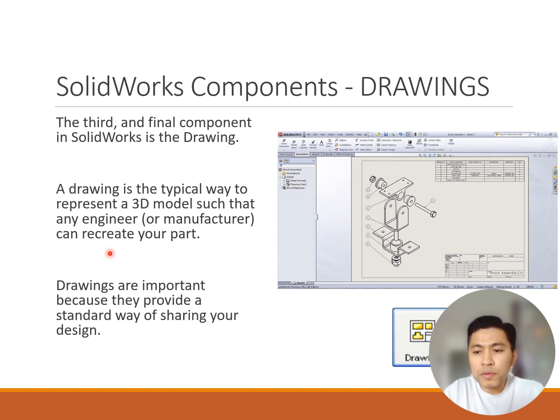The documentation consists of different drawing views and the details in the drawing views. We can detail the view by simply dragging and dropping parts of the assembly that we created in part mode or assembly mode. The drawing mode provides all the tools required to generate and modify the drawing views, and here we can also add dimensions and annotations to them.